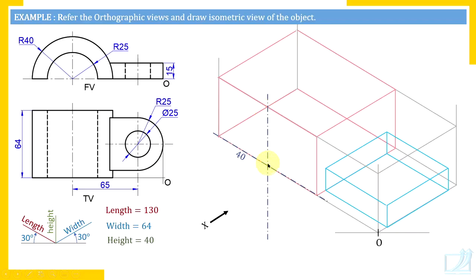Now from the center, mark points on these center lines at distance 40 millimeters from the center. So this is the center. From the center 40 millimeters upwards. So already these lines are at distance 40 millimeters from the center. So this distance is 40. This distance is already 40 up to this edge of the red colored box. Then this distance is also 40. And now here we'll have to measure 40 millimeter distance. So this distance is 40 millimeters. Now draw lines parallel to center lines.